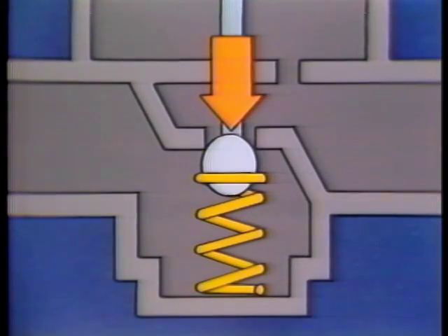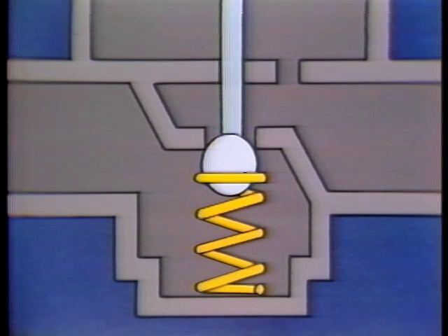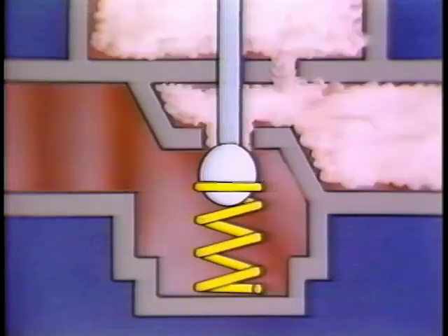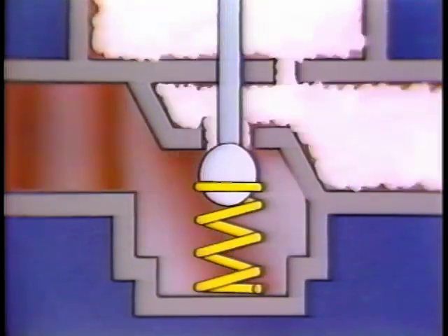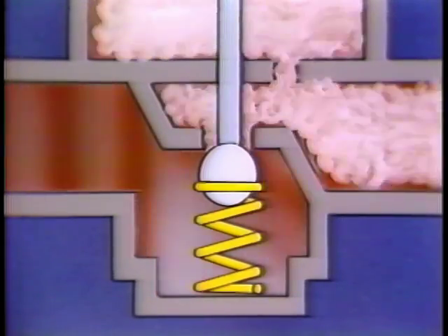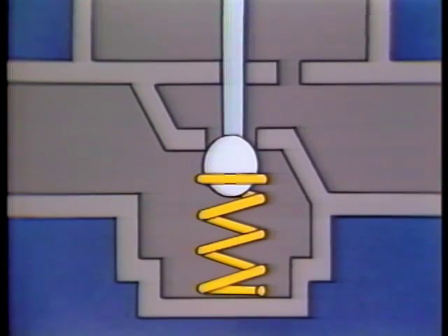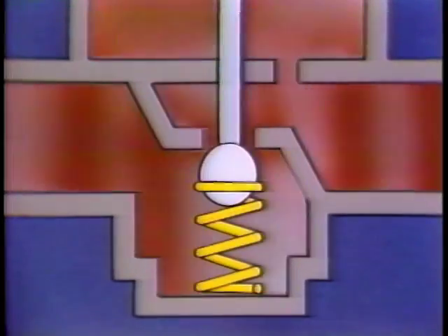When the controlled variable is a gas, which is subject to expansion and compression, the valve should open against the flow, using the upstream pressure to help seal the valve. Gas expands in the low pressure area immediately downstream of the valve when it begins to open. This pressure increase serves to quickly throttle the valve, preventing it from opening fully. When there is low flow, the downstream pressure increase prevents the valve from fully closing.